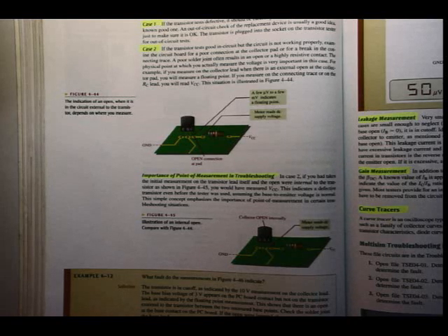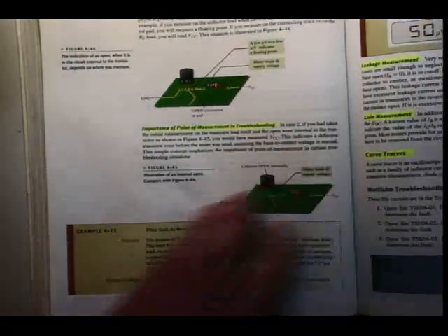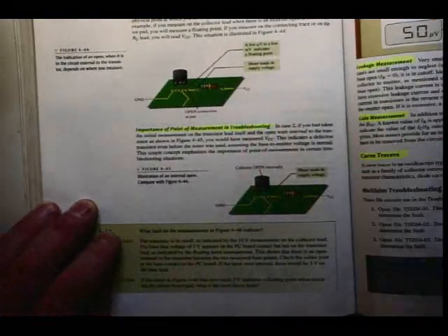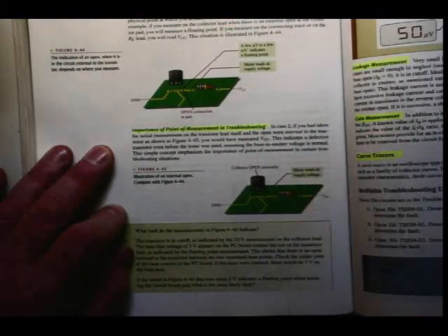You have built some simple diode circuits, application circuits, rectifier circuits on a breadboard already. And it also happens that you may have bad connections while you are making your connections on the breadboard. So make sure that your connections are good. That's the most common fault, I would say, connection faults.